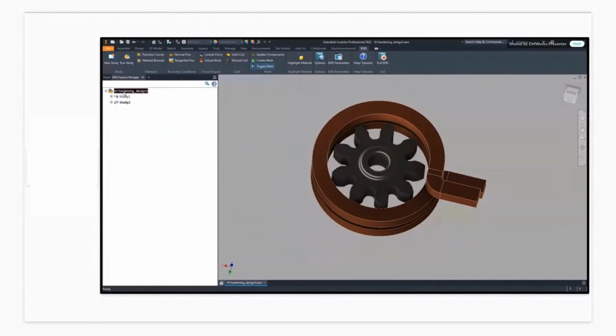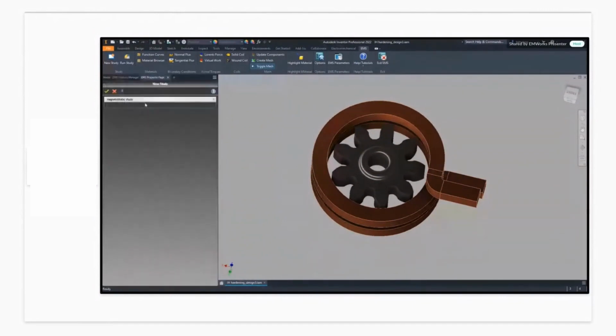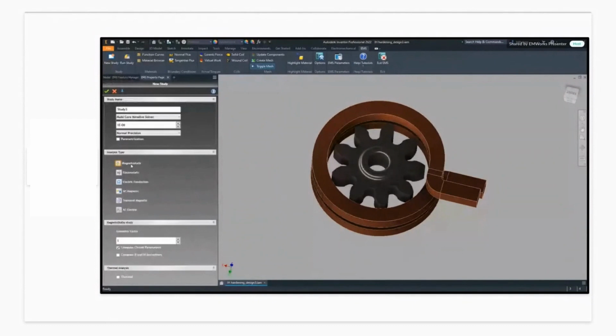In the simulation, as we will show here, you create your analysis. Analysis may be magnetostatic. Magnetostatic is for magnetic field calculation in DC. You use this for permanent magnet applications, for DC powered coils and so on. You can use magnetostatic to compute torque, forces, DC resistance, inductances, and so on. Electrostatic is for DC electric field calculation. You use it for maybe cables to evaluate some dielectric failures, some breakdown, electric field distribution, radiation, EMI, EMC, and so on.